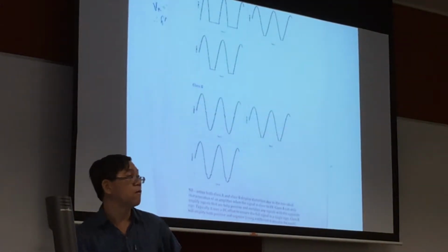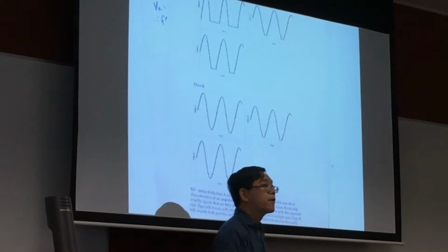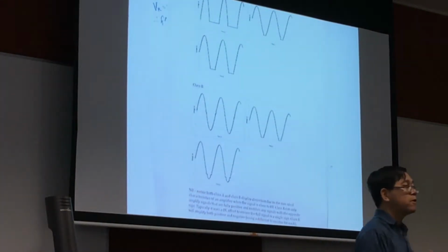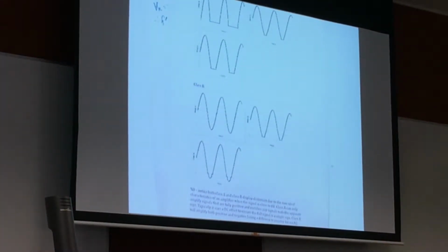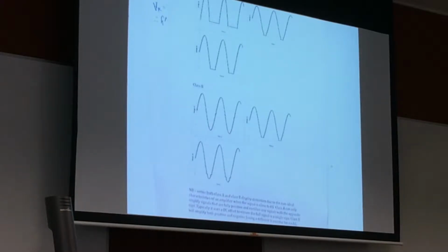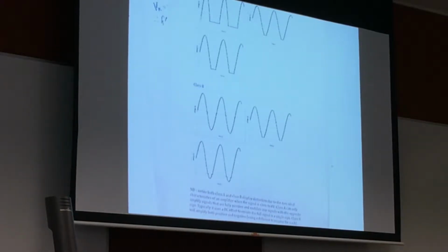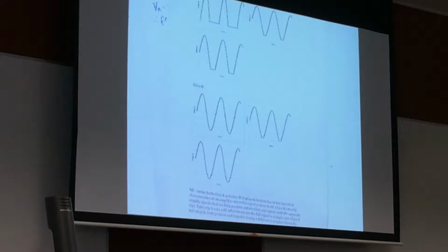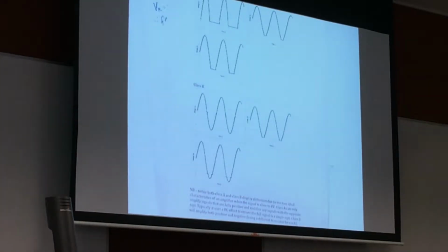Now, on the other hand, class AB, you think of it as having two transistors. One operates on the positive half cycle, the other one operates on the negative half cycle. So theoretically, they should have both cycles operating. But bear in mind that these two transistors will also need at least some small amount of voltage to ensure that base and emitter will be forward biased.